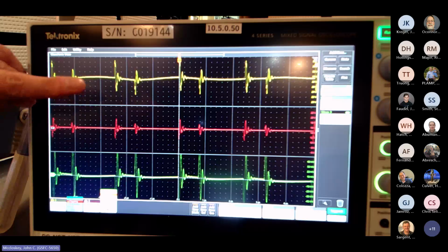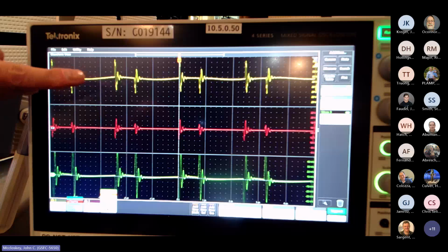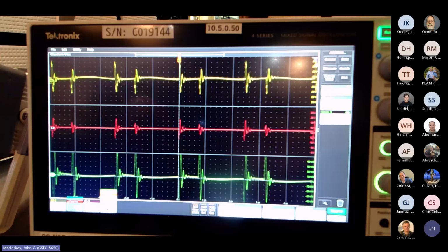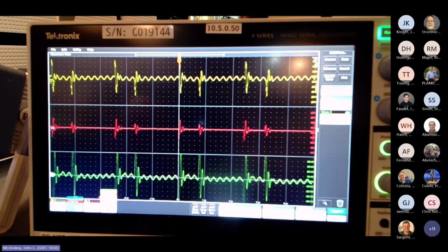There's kind of no doubt about it from what you're seeing here, but that's a voltage probe that you might not normally have access to. In this particular case, I already had that little test point set up, so I'm using it. But when you're injecting with a real system, you're establishing your pre-calibrated power level or signal generator level.